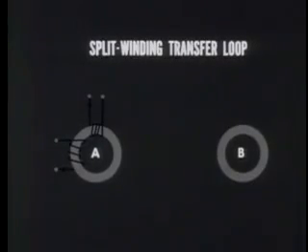We'll add 2 input windings first. The input on the left is connected so that the current flows into it on the non-dot side only. This is the one that our logical diagram showed as coming in at time t0 and setting core A to binary 1. At the top, current comes in on the dot side, setting core A to binary 0, and the time is t1.